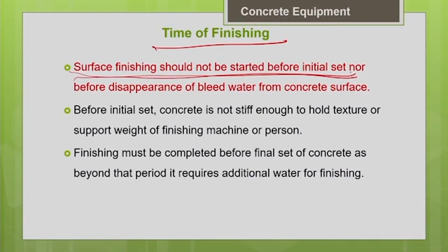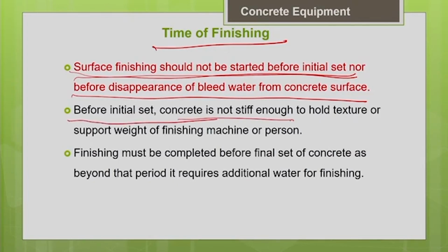Surface finishing should not be started before the initial set, nor before the disappearance of the bleed water from the concrete surface. Only after the bleed water is completely evaporated should you start the finishing process. Why? Because before initial set, your concrete is not stiff enough to hold the texture or support the weight of the finishing machine or the person who is going to do the finishing operation. So before initial set, don't try the finishing operation.